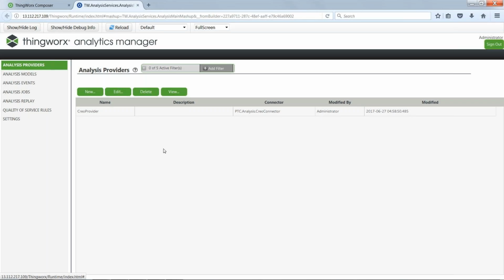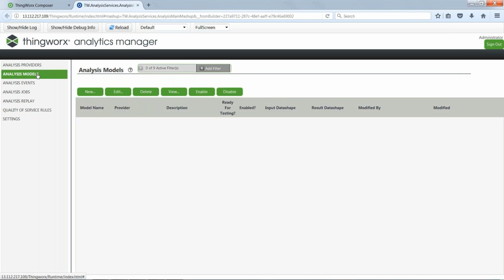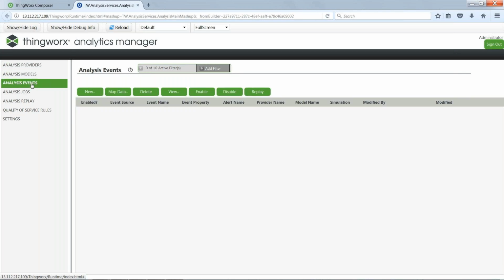Alternatively, we can come into ThingWorx and utilize ThingWorx to bring that data in for us. ThingWorx is PTC's rapid application development platform that allows you to connect into multiple systems or objects and aggregate that data into a mashup. So essentially, it's allowing you to connect out to those edge devices, whether it be sensors on a prototype or an actual object out in the field that's running, and get that data back and aggregate it into one place and make it easy for you to view. And we're going to push that data down into Creo so that we can use that in our design.